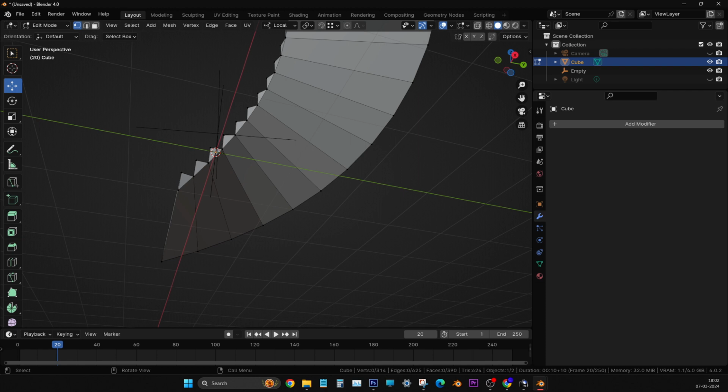Now go to vertex mode and then press M on the keyboard, merge by distance. Wait. Type 0.01 only. Enter. So it says removed zero vertices. Just select one vertex and move it and see. This one. Move it. I think it's still separate. Okay, undo.